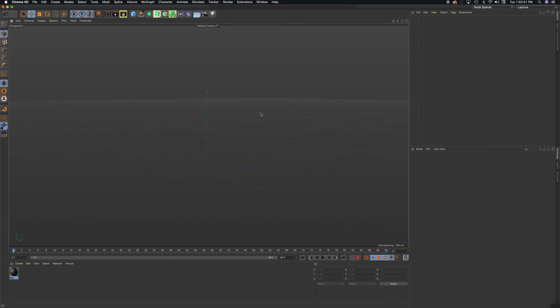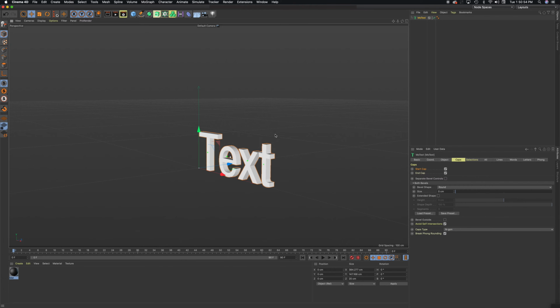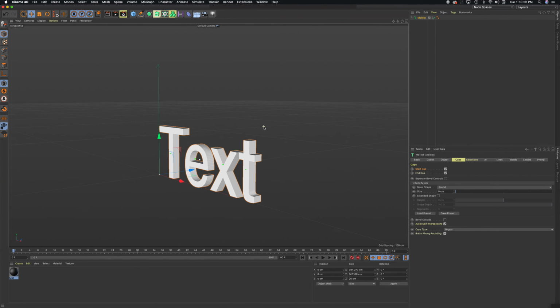In this video, I'm going to go over 3D text and how to create three-dimensional text. So, let's get started. It's really easy. If I just come up to MoGraph and go to MoText, you might have to wait a few seconds, but the word text will show up.